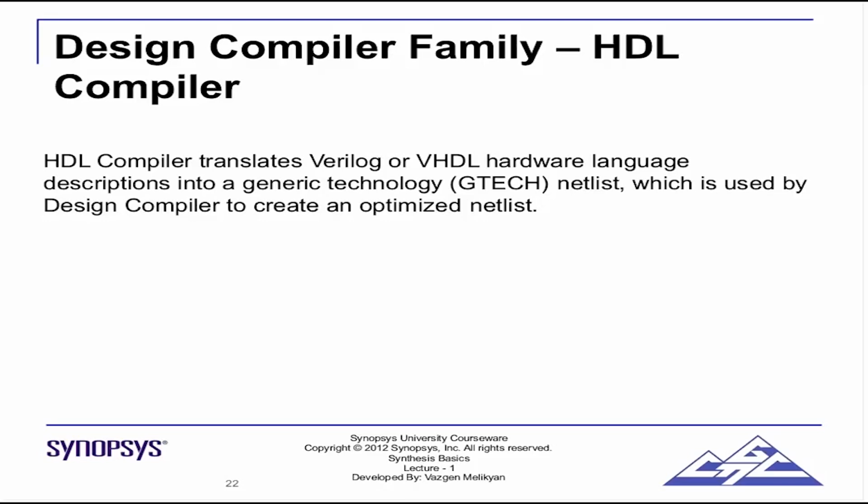So this HDL compiler helps us in analyzing if our RTL code is actually synthesizable. It will give out warnings, it will give out errors if you have cases like this. So you could use this HDL compiler in correcting your design.